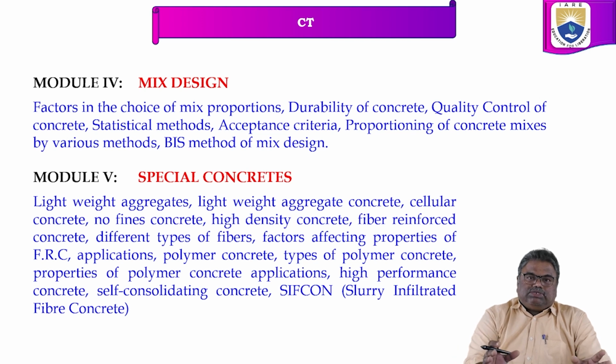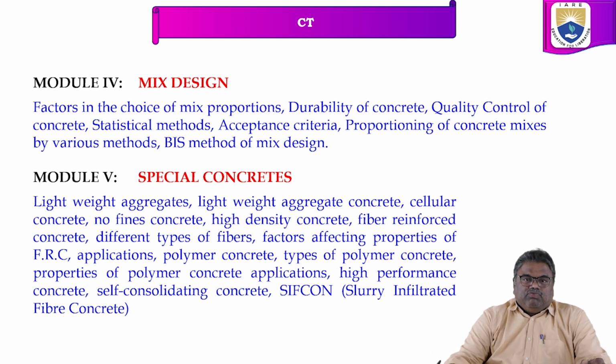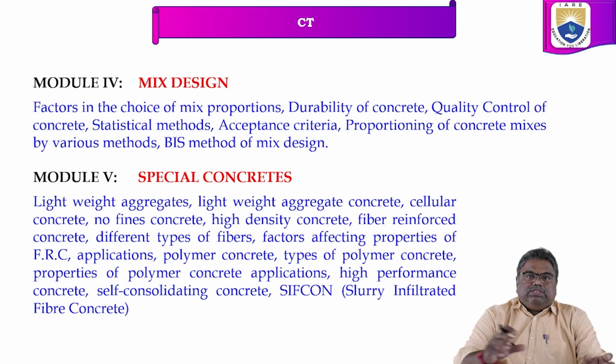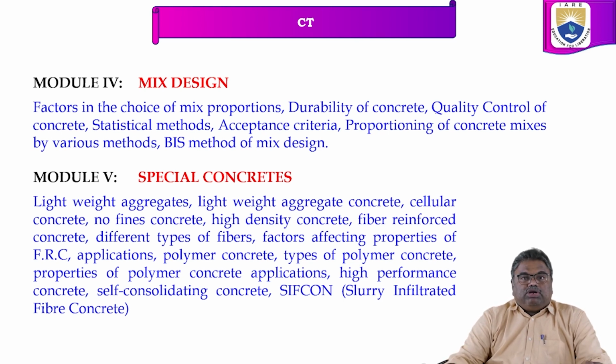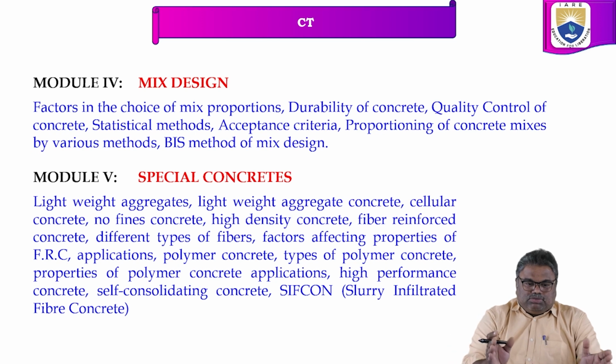If we do not reach 20 Newton per mm square after doing a mix design and casting it, we have to do it once again. We have to change the constituents, change the proportions, and test it once again to achieve 20 Newton per mm square. Once you achieve 20 Newton per mm square, then you can say that this mix design can be used at the site.